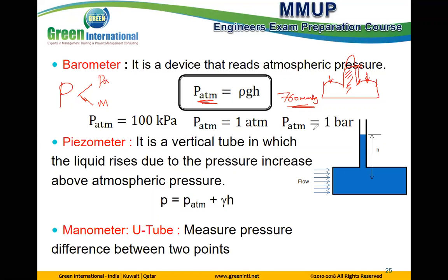It means if I give you h, I can get pressure. Both represent the same thing, pressure. I can present it in pressure form, and I can present it in head form. Same like pumps: I can say this pump is 2 bar, and sometimes I can say this pump is 20 meter head. All the same.